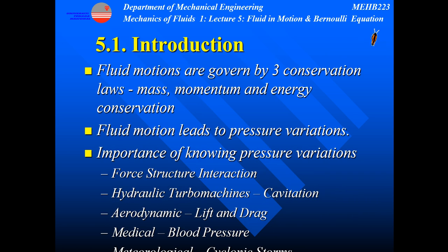So fluid motions are governed by three conservation laws, which are the mass, momentum, and energy conservation laws. So previously, you have learned that pressure varies with respect to depth. So when elevation or depth is decreased, pressure increases. So that is for fluid statics. So starting from this lecture onwards, the fluid is now flowing or moving. So this fluid motion will lead to pressure variations as well.